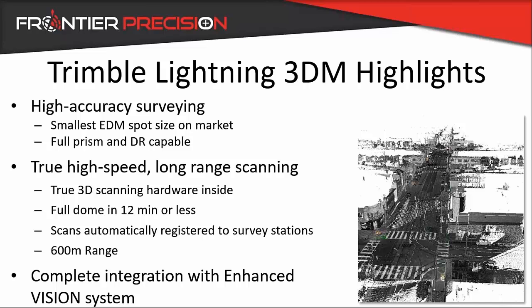Basically a full dome in 12 minutes or less. Scans are automatically registered, like I said before. There's no need to set up a bunch of targets and things like that, which we would normally do with a traditional scanner. And then one of the longest ranges in the market with a true range of 600 meters. You can see in this image here, shooting several city blocks. It's truly a long range EDM because of the other technologies. It's not just a scanning EDM.